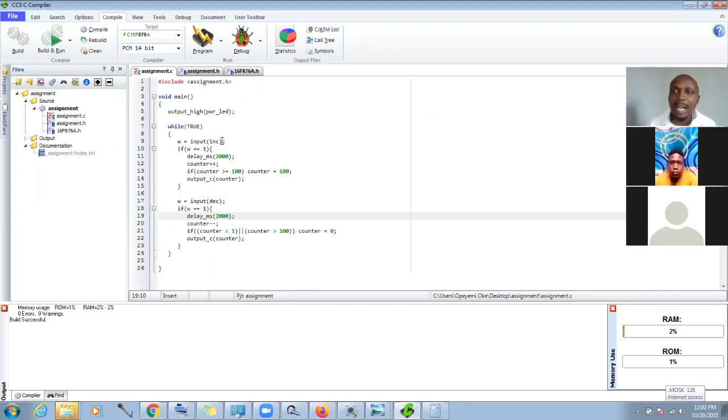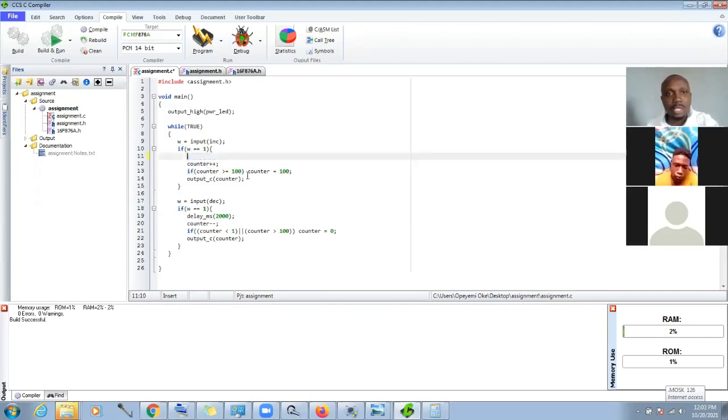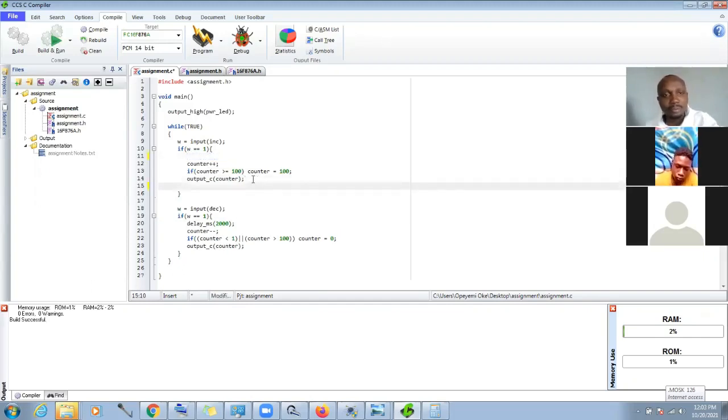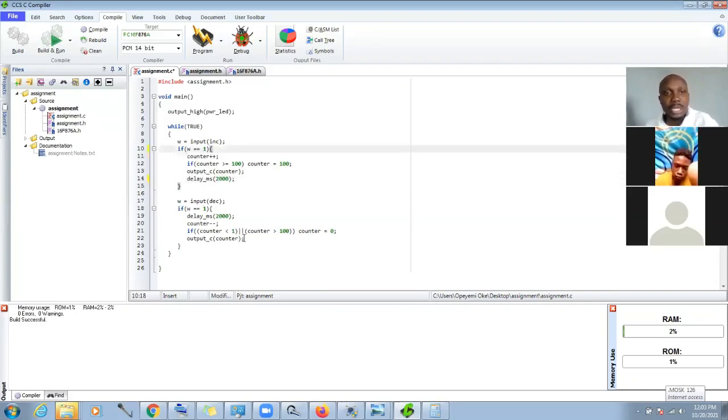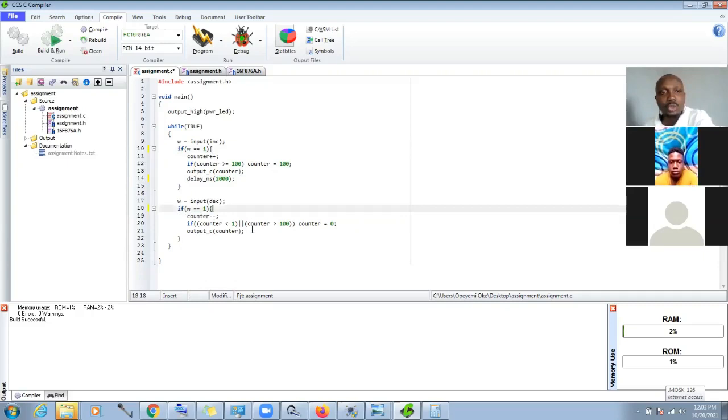The state of that pin is either high or low. Copy it into a variable. Test the content of that variable. The variable is 0 or 1, depending on your button state, whether it's active high or active low. When the condition is true, what should you do? We have asked you to wait here. Maybe instead of waiting here, what we should do is remove this and put the wait here, so that we know immediately that the button is pressed. It helps, so we are not wondering, should I press it again?